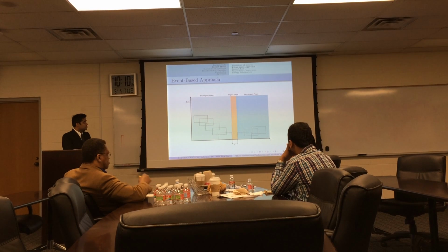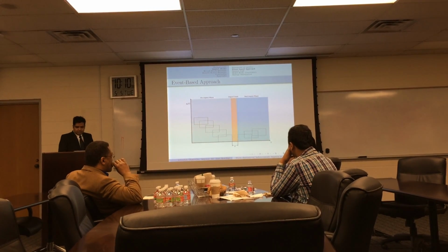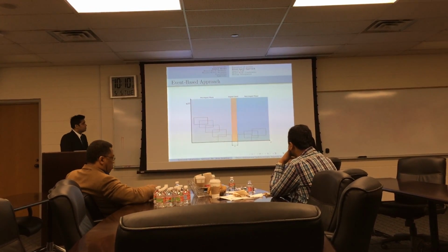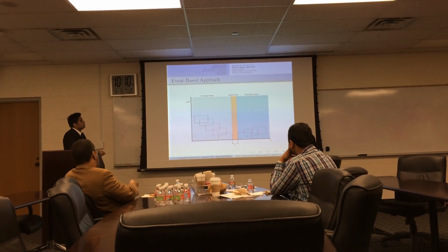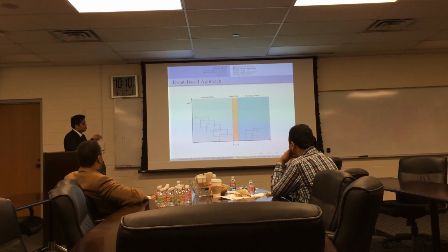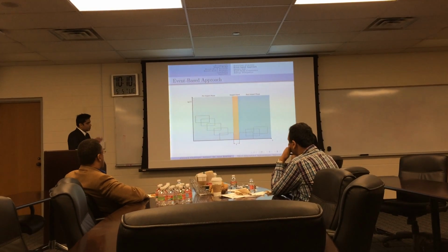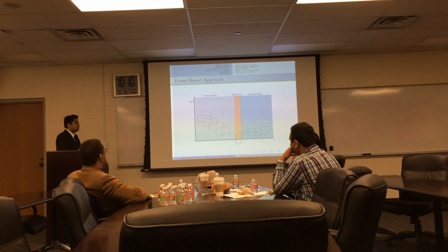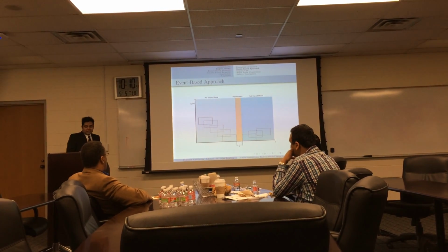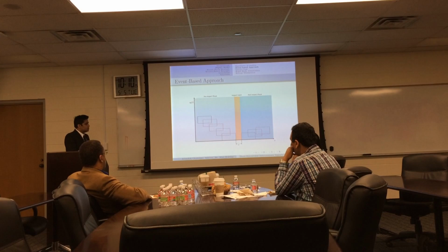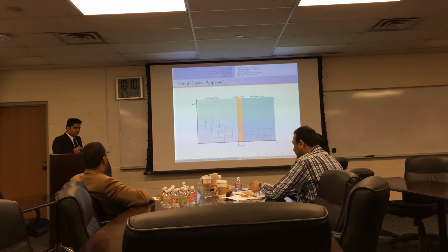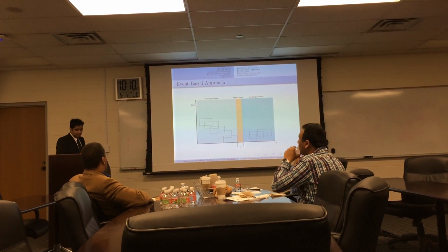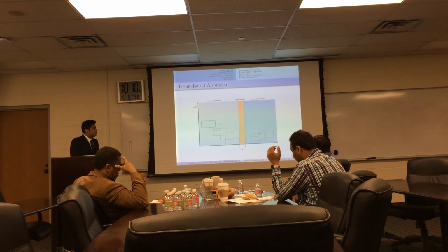So in the event-based approach that we are using, the main idea is to stop the simulation, and there are two phases. First there is a pre-impact phase when the impacting bodies are coming into contact, and there's a post-impact phase where the impacting body is leaving contact. And there's an infinitesimally small period of time in between where we are analyzing the impact.